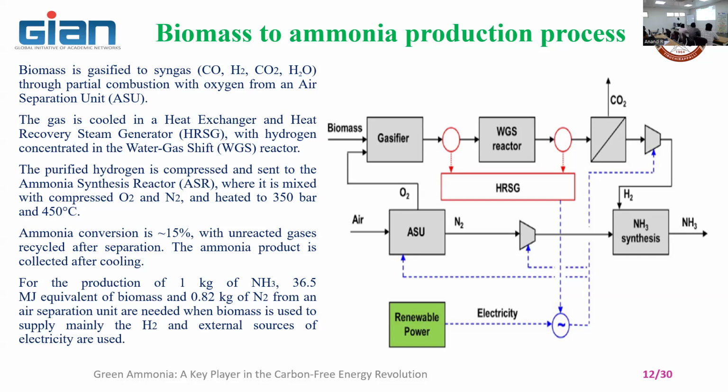It produces heat because carbon monoxide is a fuel. Actually, it's a good combustible fuel. It's an incomplete combustion product. It's not CO2. So you can use it in the gasifier itself. Recirculate it. You can use it for producing the heat for producing the synthetic gas. So you reloop it. Then the CO2 will be entering into the gasifier.